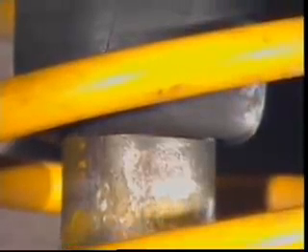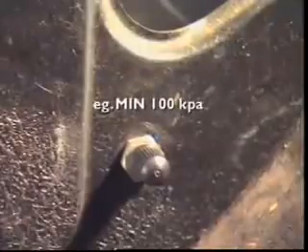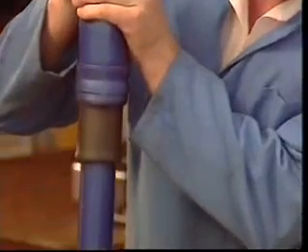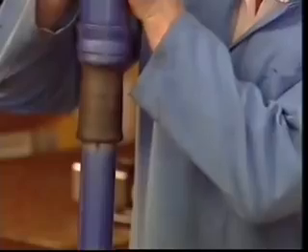When the load is removed, the extra air is released through a filling valve, which allows the suspension to return to its original settings. A minimum air pressure must be maintained in the cylinder to prevent tearing of the rubber as it collapses internally with shock absorber action.